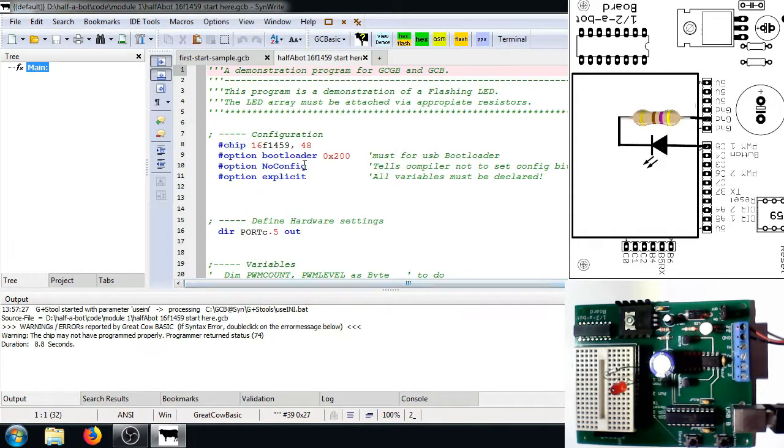Right, now you will notice that nothing is happening. Our LED isn't flashing. This is because the chip is still in bootloader mode. So if I want to download another program or a little adjustment to the same program, it will do it, but it's not going to run the program. How do we get out of bootloader mode? Well, we press reset, and once we've pressed reset, no joy. Now I pressed the wrong button. Reset. There we go. I just had a little blonde moment there.